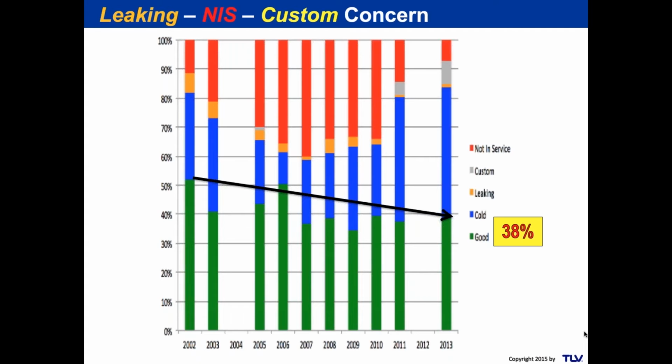But interestingly enough, we're talking about condensate returns today. So here is what we're concerned about. The not in service traps might have been leaking, and then somebody just valved them out and said they were not in service. Now, they truly might not be in service. We don't know that from this graph. And they've got 1 or 2% of traps leaking, which is the orange.